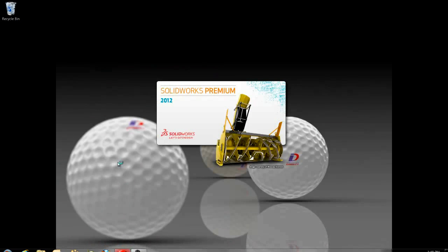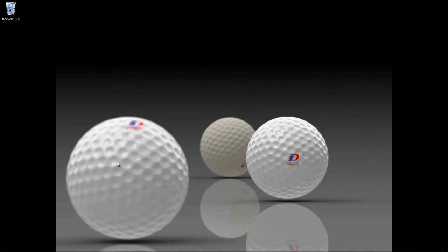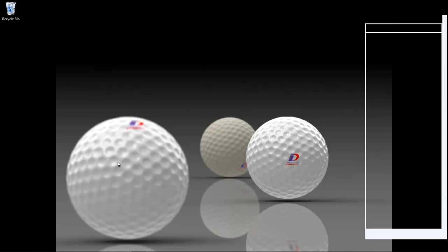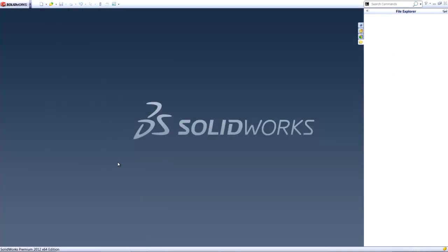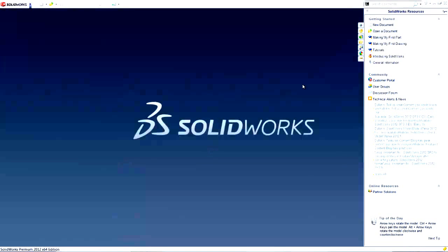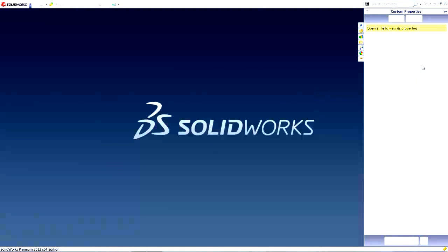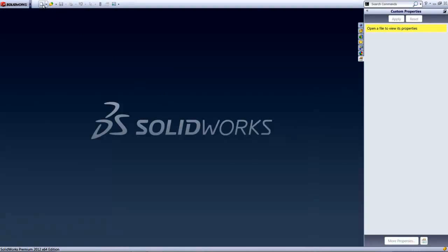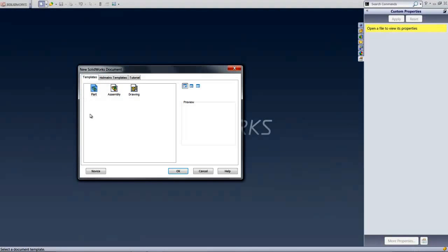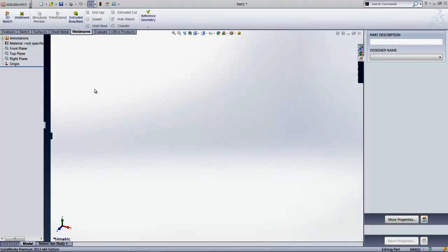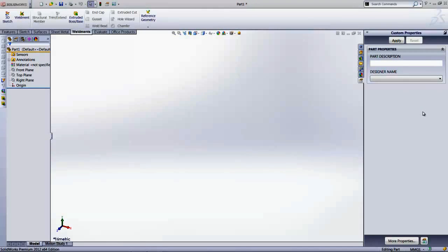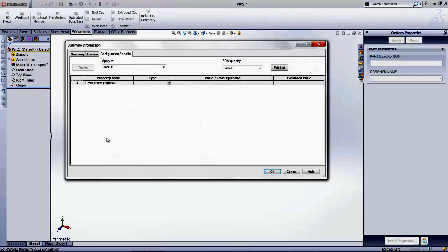Now if you were to start up our SolidWorks, what happens now is that the interface has changed slightly, and you'll see now the benefits of how creating a custom property tab would be useful for users in the long run. First and foremost, you would find that the custom property tab is still empty. But since I've created a set of properties for my parts, let's start off here by opening a new part, and automatically the interface that I created earlier has been updated accordingly. Right now, first let's start with a before and after scenario. Before, right now,